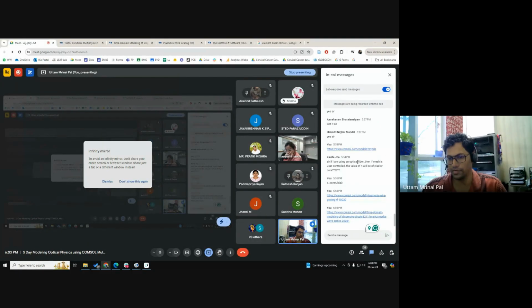Okay, so Kavita had a question. If I'm using optical fiber, and the mesh is user controlled, will the value of n be for the clad or the core? Optical fiber we will be doing on day 3 perhaps. When that time comes, I will talk about it. Basically in optical fiber you're doing mode analysis, right? For mode analysis, you don't need physics-controlled mesh, because the modes of the optical fiber are not dependent on wavelength. It's a spatial parameter. Only for the propagation do you need to modulate with the wavelength.